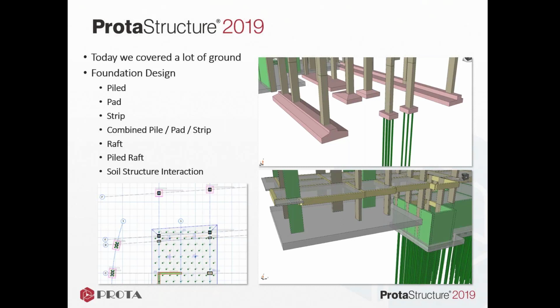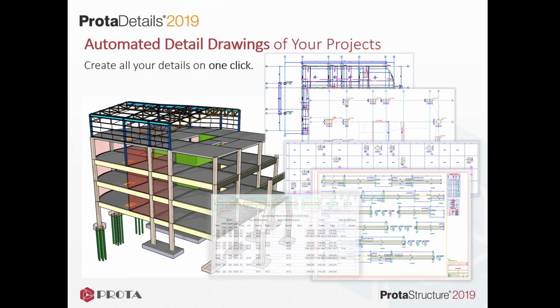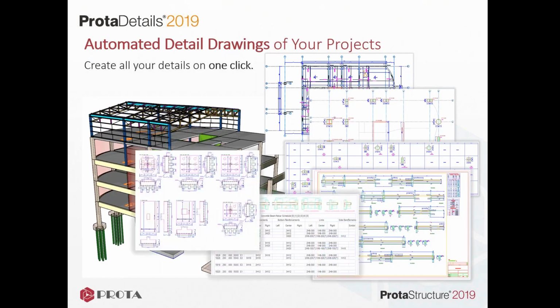You can also define irregular foundations, and foundations can be defined at different levels, as you can see in these views here. And finally, we moved on to document everything. So you saw how those were then created within Prota Details, and how you can just extract what you want from the model out into nice and neatly arranged drawings together with all the quantities takeoff.